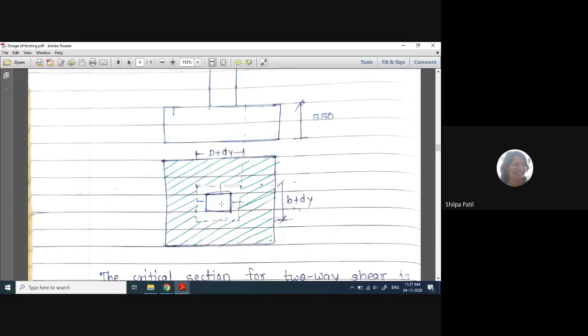So it is like punching at a specific location on the footing. And because of that, a certain area surrounding the column gets stressed, and these stresses are always the shear stresses. So this particular area gets subjected to punching action because of the excessive shear stresses acting below the column, along the perimeter of the column, and also up to a certain region surrounding the column.